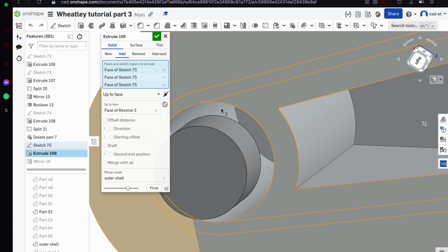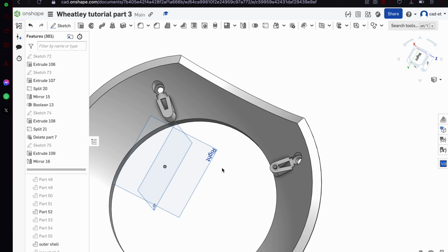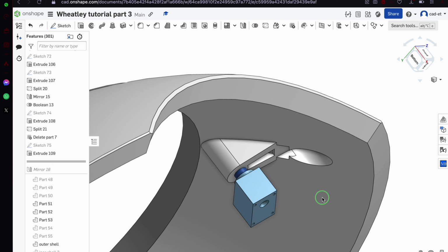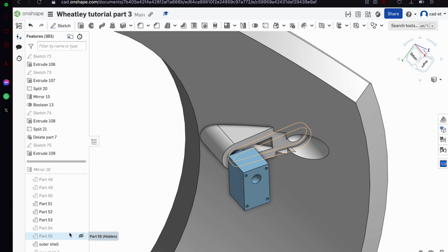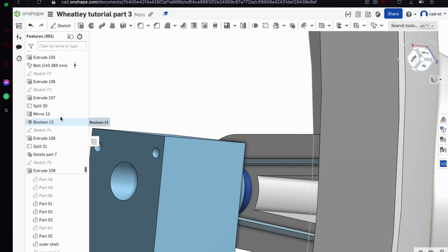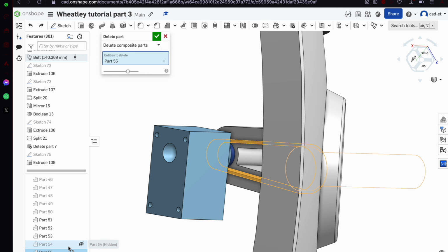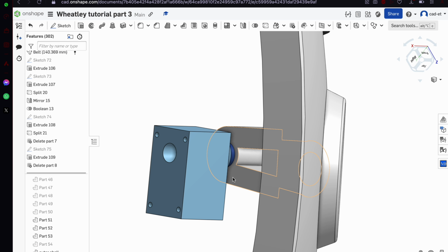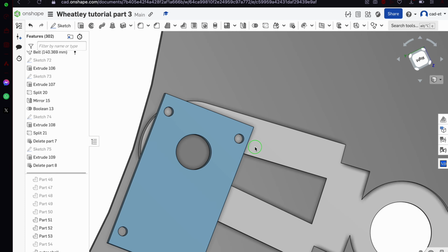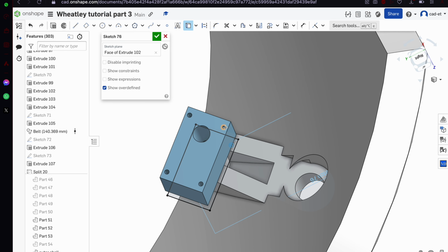And then you can see the problem here is that the pulley would simply fall into the design, into the bearing stop thing. So I've reduced the size of the hole so that the motor doesn't drop in, and that the actual pulley is locked against the frame. There would be a thrust bearing underneath it to allow it to rotate constantly without rubbing against the mount that it's attached to.